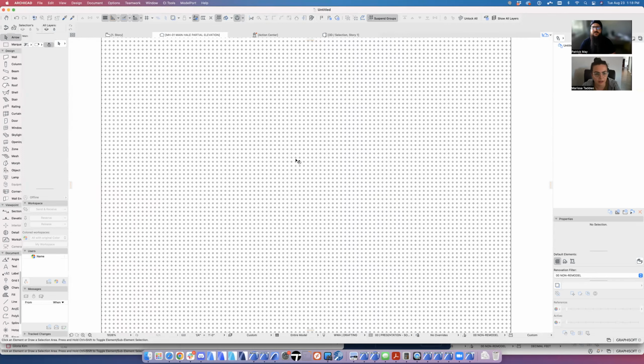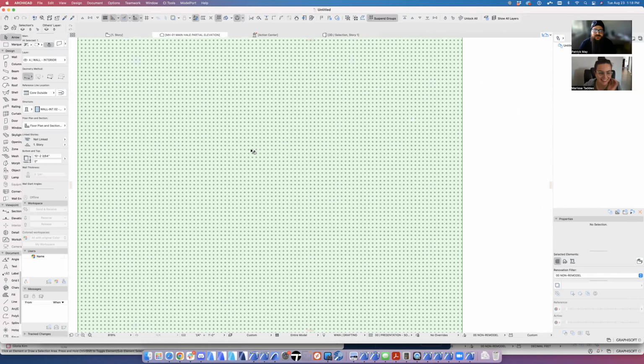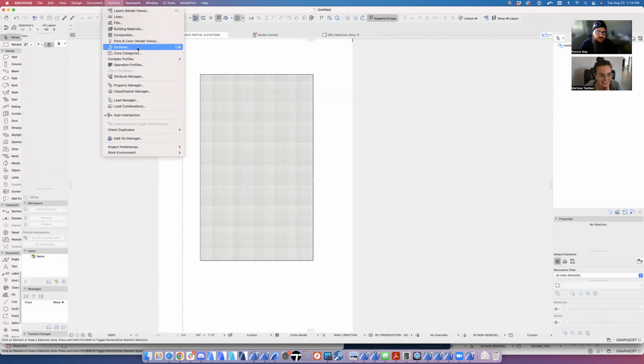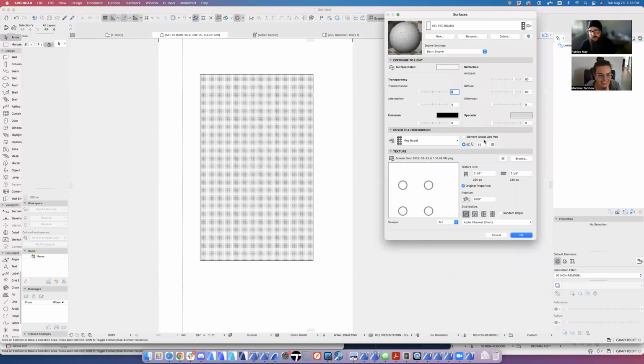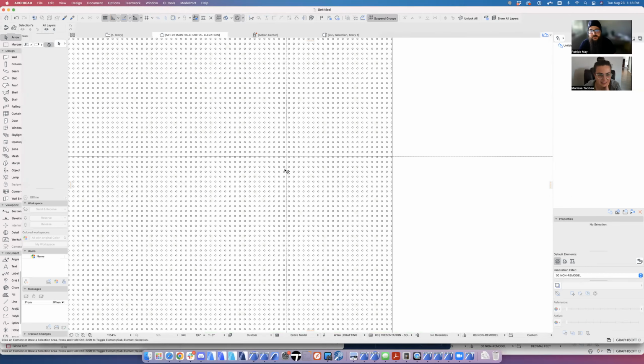It's a little bit nauseating to look at. And then if that surface is just too bold, too dark, you can go back to your surfaces. And the cool thing about this is it's like a global control. So if that's just too dark, I can bump it down, and then project wide, it's going to be using that lighter gray pen. So now there's no drafting or anything to apply that surface to the elevation or the 3D model.